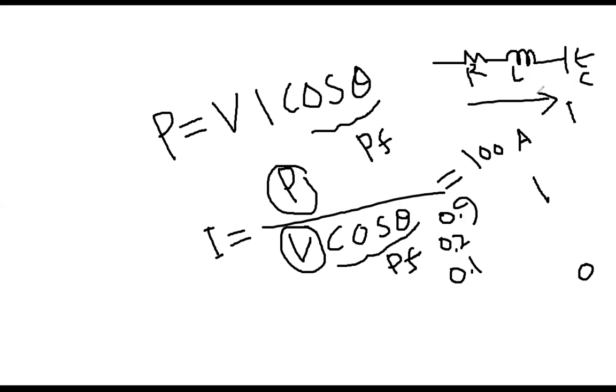So what is the impact of higher current? Just look at this branch, RLC. For example, you get a higher value of current and then I square R. What is that I square R? Power loss. So, as Manoj explained, there will be higher power loss. Similarly, for this component, there will be I square XL, I square XC. Even the reactive power loss will be higher.